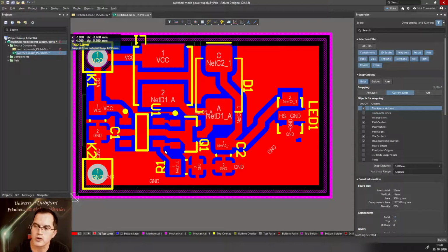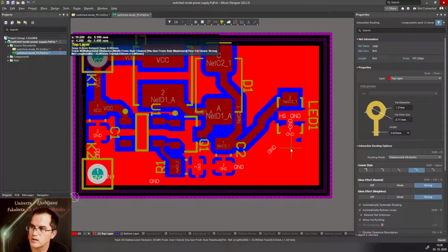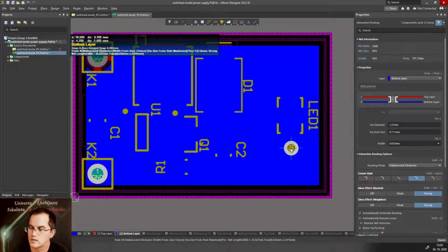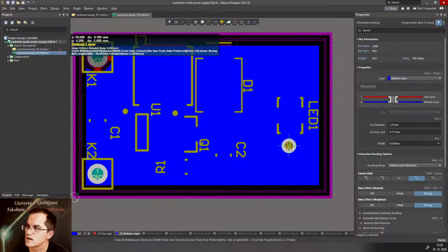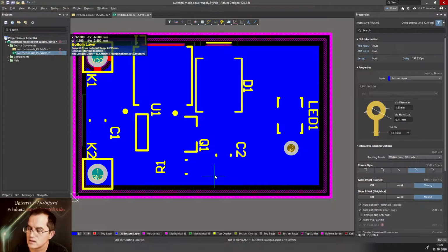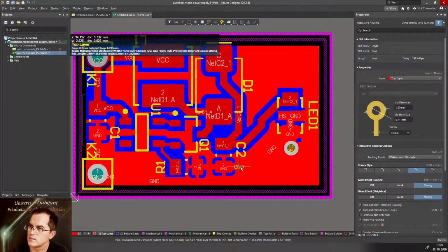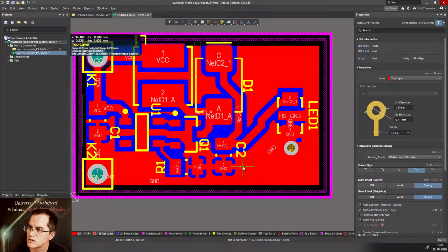Now we have a bottom ground layer, but that bottom ground layer will not help if we don't allow the currents to return on them. So every ground pin that we have should be connected to this bottom ground layer, like that one. Let me make it smaller. There is no rule here in this design for smaller wires. Okay, I will put them as they are. What else? Here. Maybe I will put a wire in between. Maybe I will put it here.